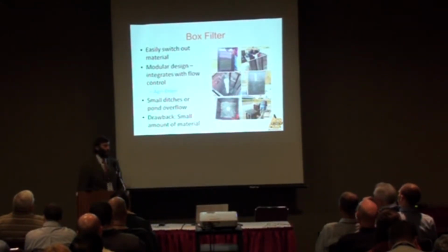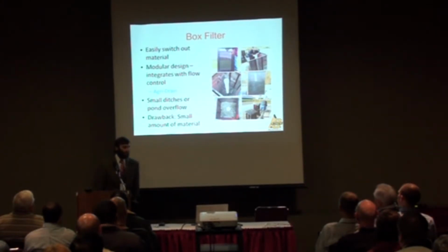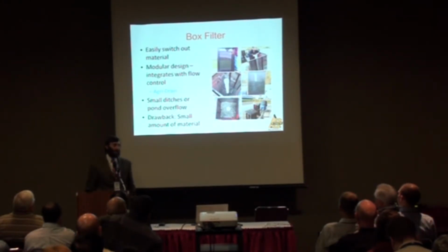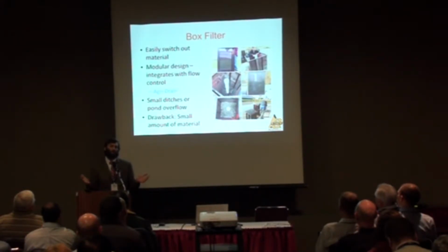We have a box filter. This particularly was built for a pond. Nice thing about these box filters is that you can easily switch out the material. These large perforated boxes can be placed strategically to treat the water that exits a pond as it leaves the pond. It's kind of like a riser pipe.